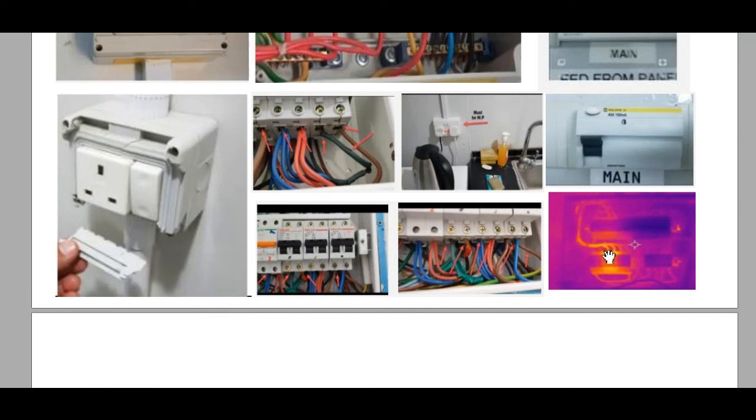As you see here we have a thermal image. Here we have a big loose connection in the panel. You see this one, and as I remember this is approximately 52 degrees centigrade for this one.